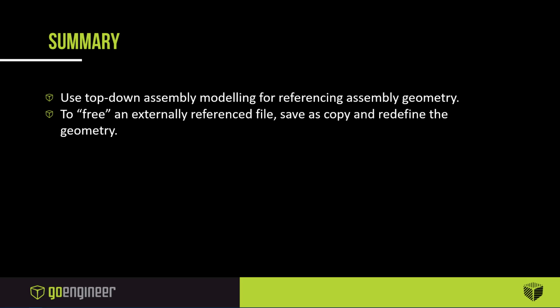Okay. Is it better to drive virtual parts from other parts or sketches? So I've seen it most commonly done with other parts, but you can do it with sketches. You could make an argument that because a sketch has less data to resolve, that a sketch is better than another part, but it's definitely most common to use it with parts.